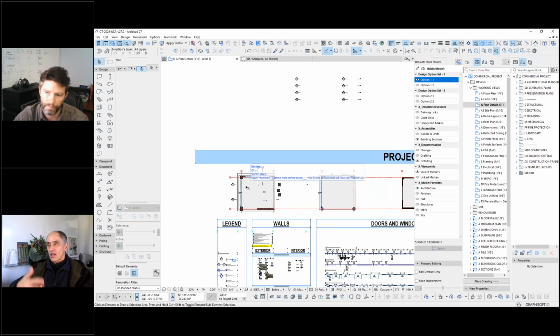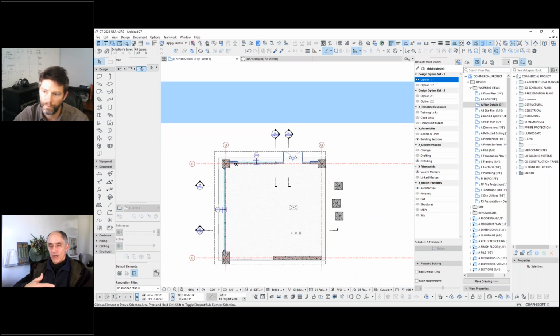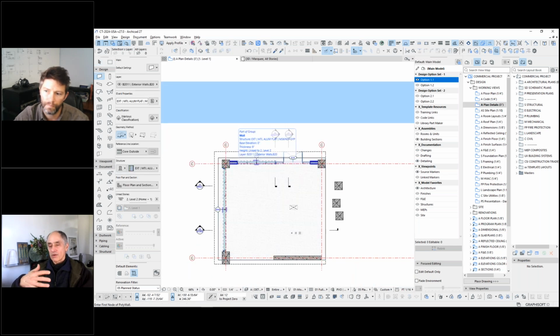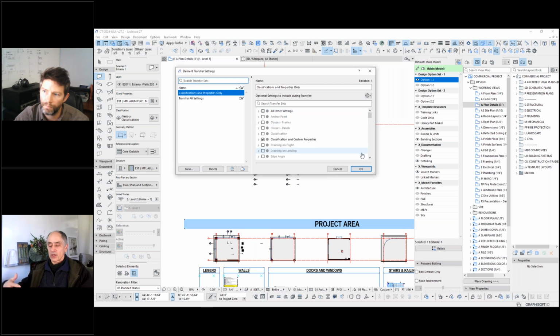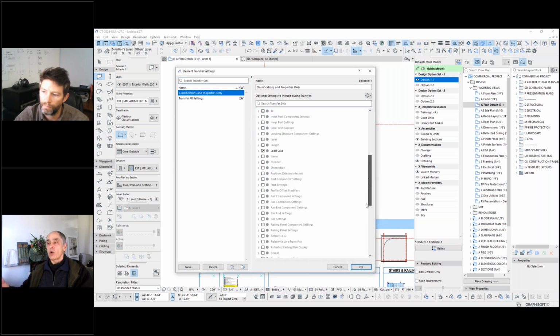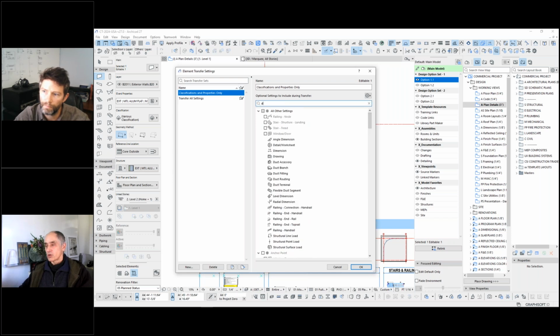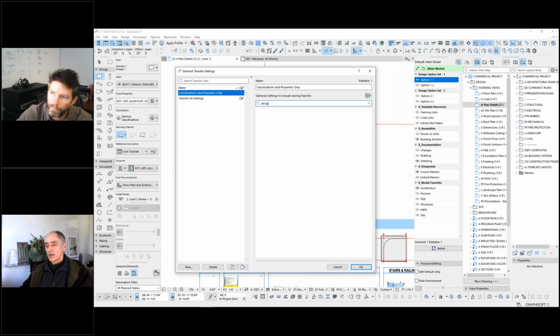But the cladding is attached to the one element, whichever one is visible, or maybe both are visible if they're not using design options. It's not like the cladding is a single thing. It's a cladding associated with the wall, just like a window is associated with a wall. And if you were to drag the wall, the window goes with it. So that may make it clear.